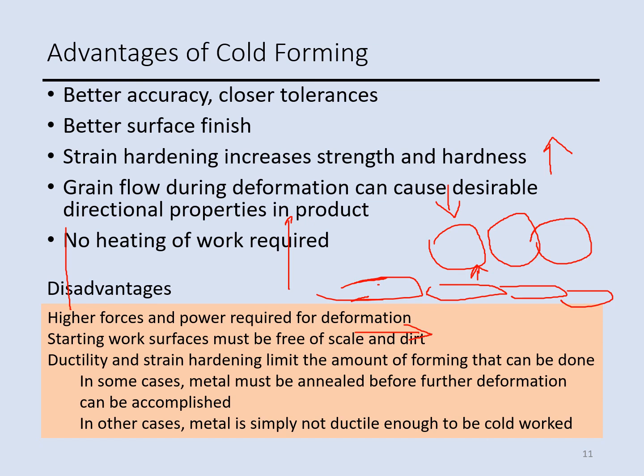But there are some limitations, some problems with cold working that we have to consider. First is that because we are performing the process at room temperature, we need more force. We need higher force and power for the formation. And the starting workpiece should be clean.